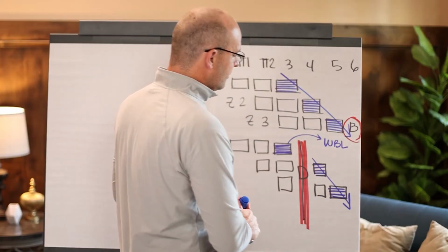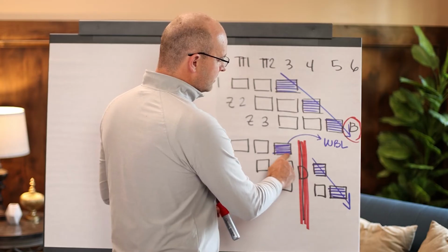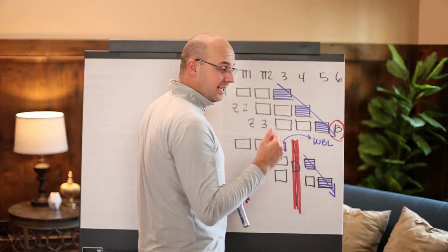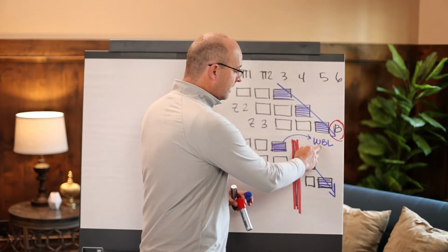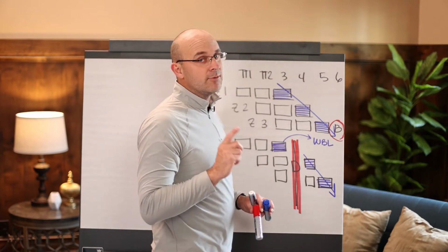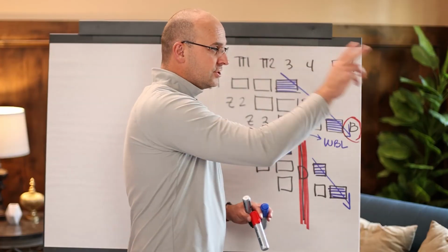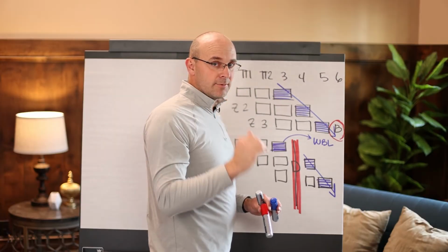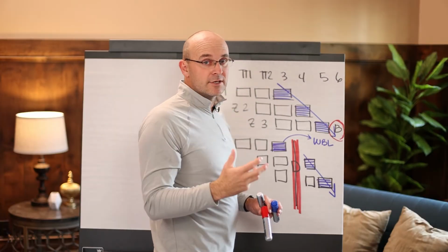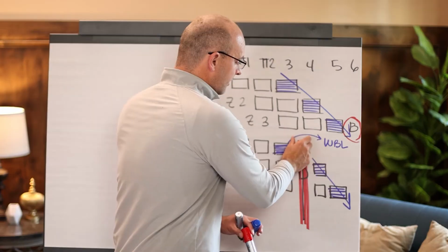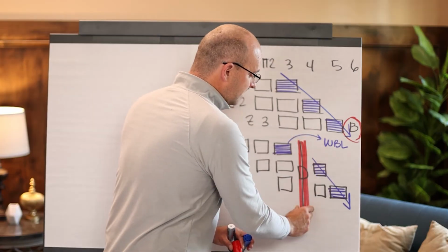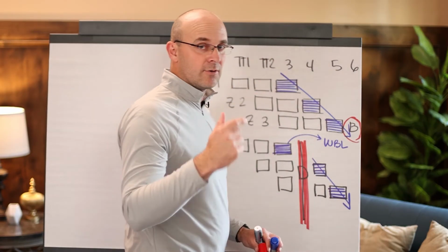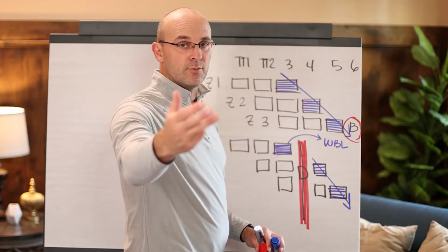So the other thing that you can do is you can simply stop this trade during this delay, and they can stop, wait, and prepare. Not even go do workable backlog, and they will make more money than if you shift them to another project and move around, because they're waiting, they're preparing, they're cleaning up their tools, they're training their workforce, and they're absorbing and fixing that delay so that they can start out right again on schedule with good production.